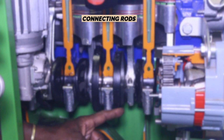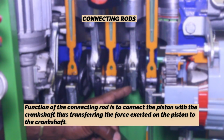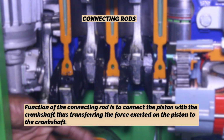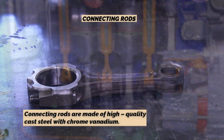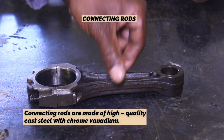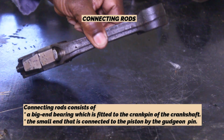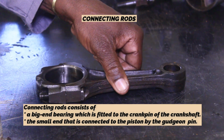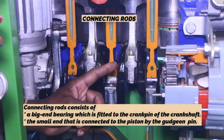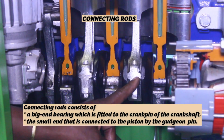Connecting rods. The function of the connecting rod is to connect the piston with the crankshaft, thus transferring the force exerted on the piston to the crankshaft. Connecting rods are made of high quality cast steel with chrome vanadium. Connecting rods consist of a big end bearing which is fitted to the crank pin of the crankshaft, and the small end that is connected to the piston by the gudgeon pin.